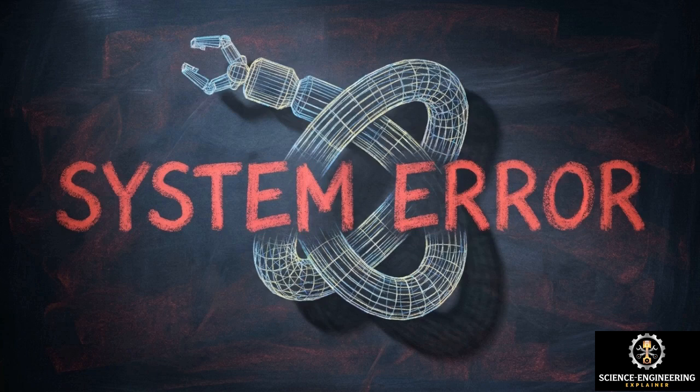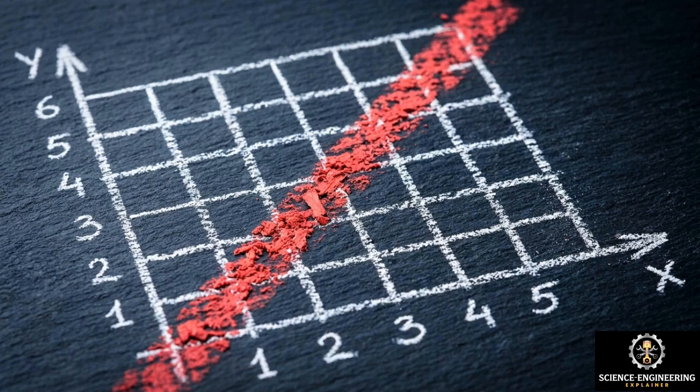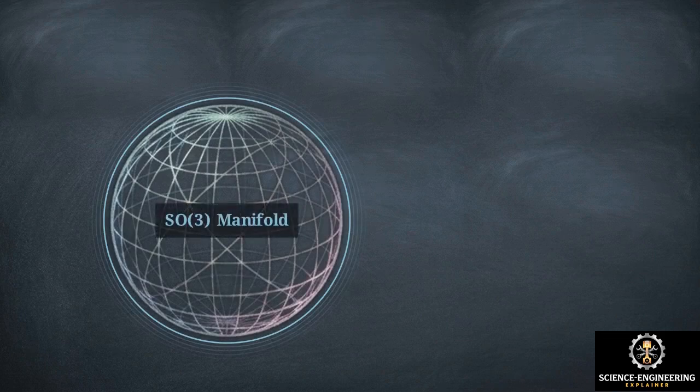If you apply straight-line linear math to robotic orientation, the system experiences a catastrophic failure. This happens because orientation does not live in flat space. It exists on a highly curved, non-Euclidean mathematical manifold, known as the special orthogonal group, or SO3.